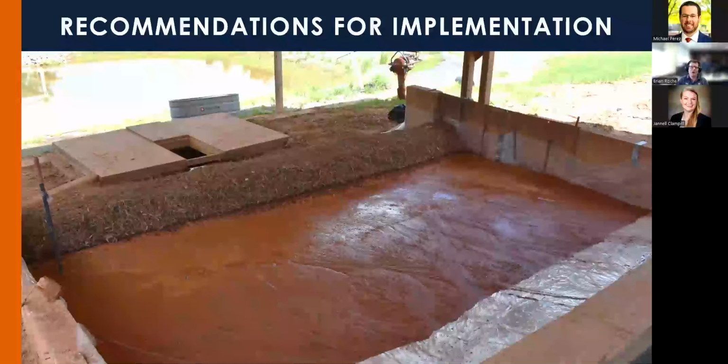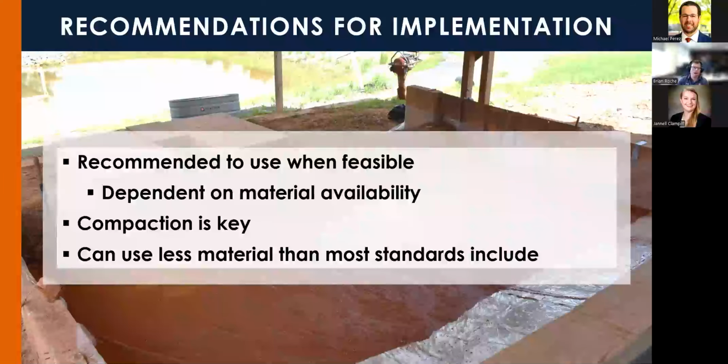Based on our results, we recommend the slash mulch berms be used when feasible, because we saw higher performance compared to other sediment barriers, as well as it being more environmentally friendly, as you're able to just leave it on site and it does not have to go into a landfill, and there are not as many emissions associated with its production. What we really saw was that it depends on material availability. In our conversations with the people from Nebraska DOT, they love to use it, but a lot of their construction sites are not wooded, so they don't have the material to use.